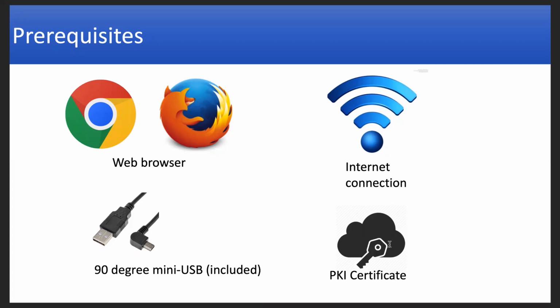There's a PKI certificate, that's a public key infrastructure or security certificate, for your field commissioning device, a laptop or tablet, whatever it may be. And that PKI certificate needs to be loaded onto the device, onto your laptop, before commissioning can be completed.